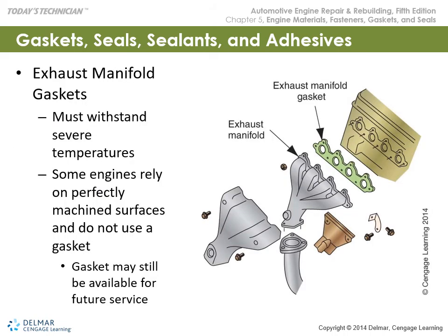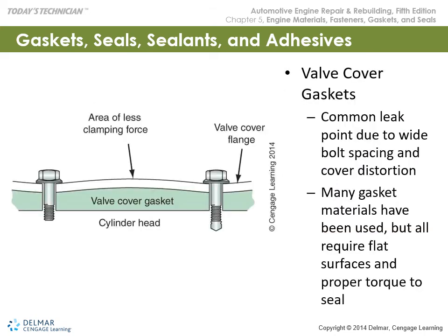Exhaust manifolds, extreme temperature. There's some thin metal is used in some applications. Gaskets may still be available for future service, but in the real world, we're going to be replacing anything that has been heated and cooled that many times. You're going to have to surface the block side, and you want to surface your manifold side and make sure that everything has been cleaned and new hardware is installed. Hardware that's been heated and cooled many times is virtually non-serviceable.